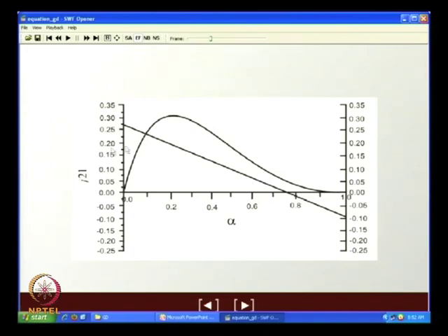Because for this particular J21, this curve we have drawn is for a particular u infinity and n, for bubbly flow pattern. Accordingly, we have selected u infinity and n. Therefore, the point of intersection should be such that it lies in the bubbly flow pattern. When does bubbly flow occur? Low gas, high liquid. So, we will always have the point of intersection between alpha equals to 0 to alpha equals to 0.3 or something of this sort. Okay. And what next do we observe?